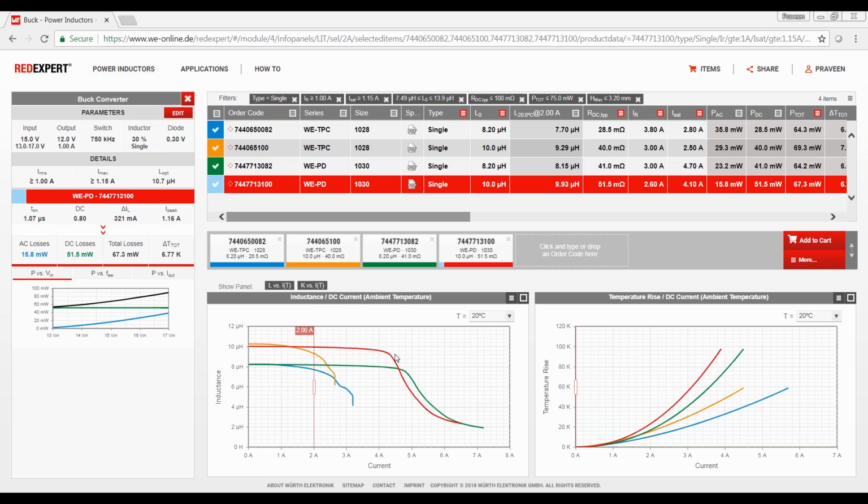As far as common mode choke is concerned, you can directly go to this tool, and we have considered 50 ohms of system impedance for the common mode chokes, and we have already created the attenuation graph for it with respect to frequency. So you can directly go into the common mode choke module and find these components based on the attenuation that you need.